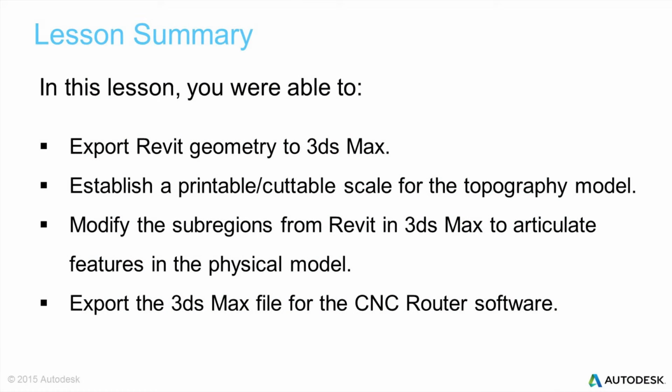So in this lesson, we were able to export Revit geometry to 3ds Max, establish a printable cuttable scale for the topography model, modify the subregions from Revit in 3ds Max to articulate features in the physical model, and export the 3ds Max file for the CNC router software.